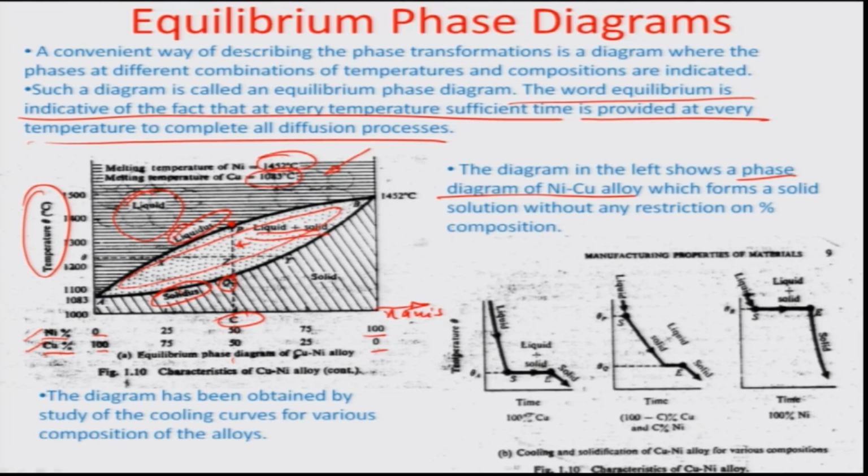And how will you plot it otherwise for a single phase? For example, you know that for the 100% copper phase, you have a single temperature beyond which the conversion would take place. So, here you can see on this particular diagram, if the copper is 100%, the temperature at which the conversion is taking place is exactly 1083 degrees Celsius, which is the melting point of copper.